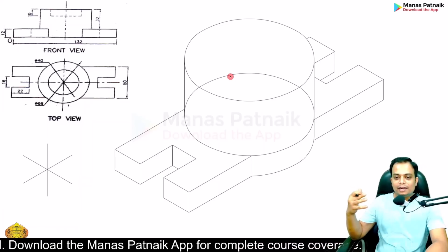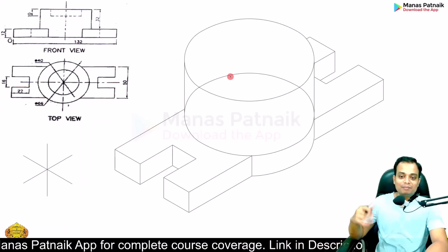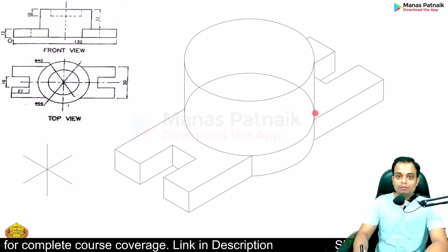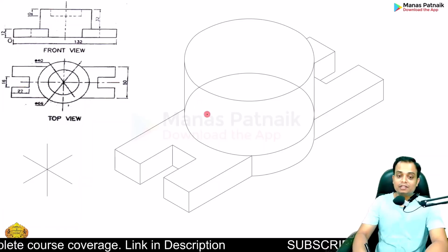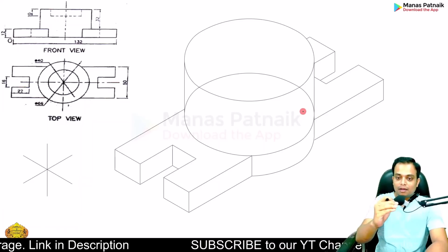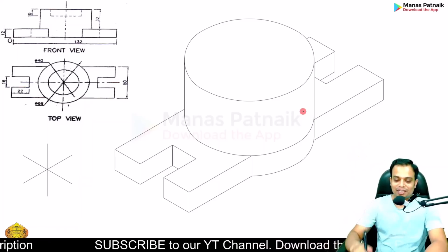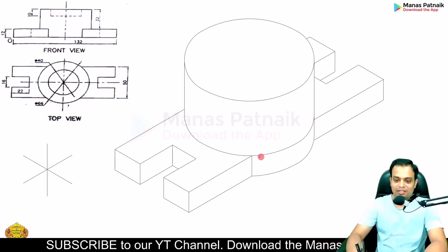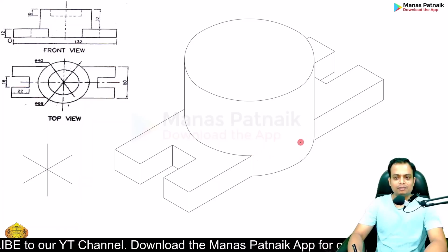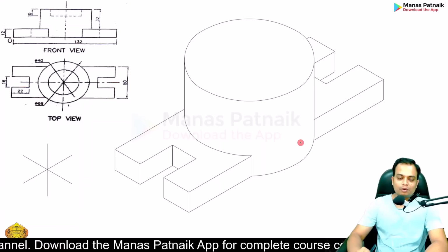This elimination of all of those lines which eventually won't be seen in the isometric view gives us a lot more clarity. But we need to bring more clarity, and in order to do that, I am going to get rid of this curve also, which actually falls behind this curved surface or lateral surface of the cylinder. One more thing is left. What about this? Why is there an edge? There is no edge over here. So get rid of it. Done, sir. Very clean. Now our drawing looks very, very clean.